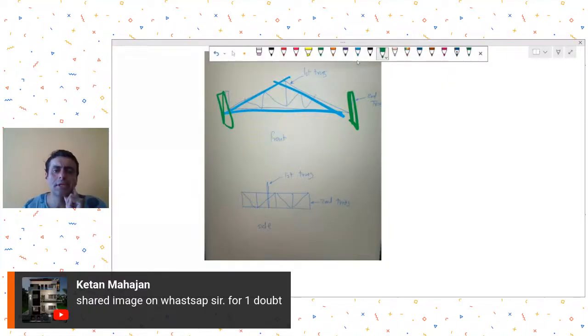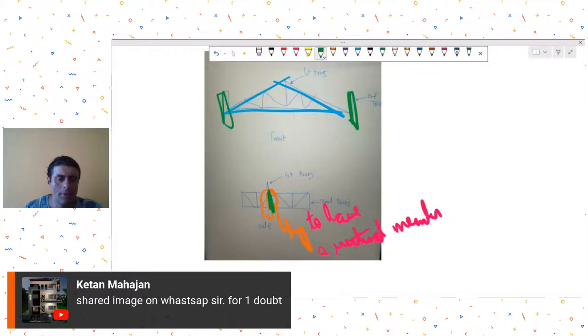So generally what we do in such cases, this becomes slightly complicated, and it will depend on your situation also. First of all, try to have some vertical member of the second truss over here. Try to modify the geometry in such a way that there is a vertical member of this second truss at this junction. So there must be a vertical member that you have over here.